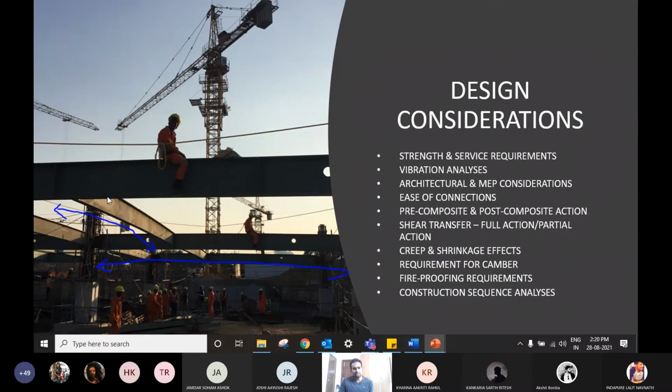They are the ones helping the beams that are being dropped slowly by these cranes. The tower cranes pick up the beam and place it. And these are the guys who guide the piece of the structural component to sit, and they quickly provide some bolts inside. So it's kind of fixed. And you need to tighten the bolts later to make it permanently fixed.